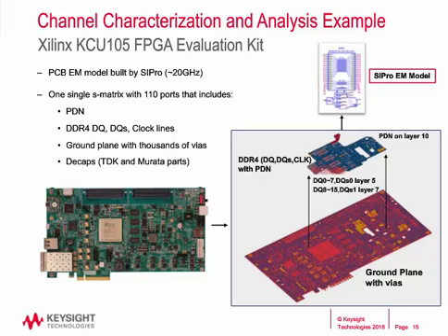It is important to note that the S-parameter contains mixed reference impedance, very low for PDN. In this case, it was 1 milliohm and 50 ohm for the channel.